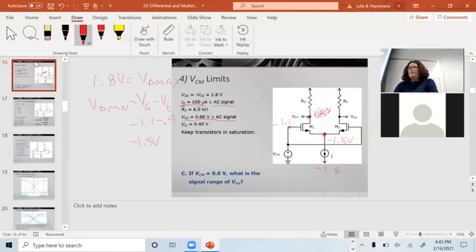The way we keep these things stable and still have a differential signal on the input is we put a feedback resistor, or some kind of feedback loop, between the negative input and the output. That cuts the gain of the circuit down to a point where it's like 5, where I can actually use it as an amplifier.